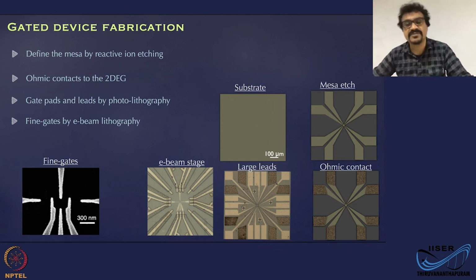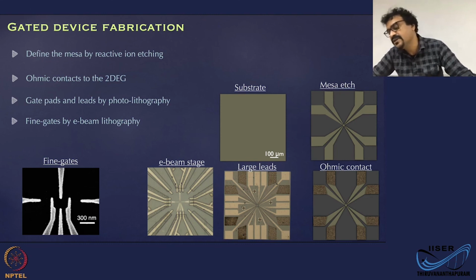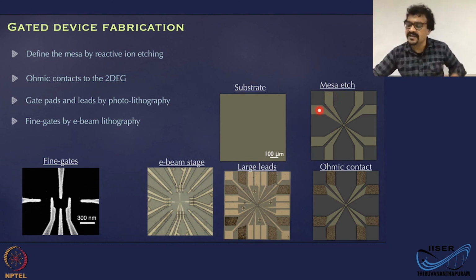Assume that this is a silicon substrate for the time being, a silicon germanium 2-dimensional electron system. You assume that. Okay. And the typical dimensions are shown here. And one of the first steps that you would do is remove the material, or remove the 2-DEG, wherever you don't want it. So you will etch down regions where you don't want the 2-DEG by photolithography. Once you etch it down, you will get a profile which looks something like this.